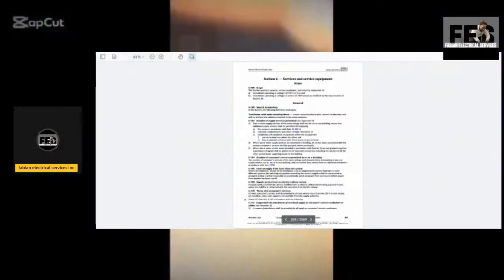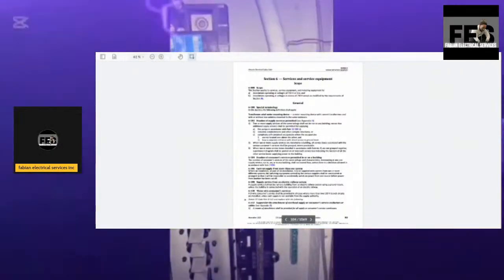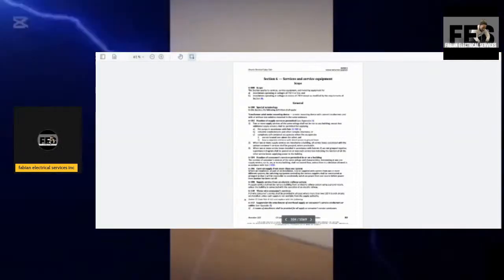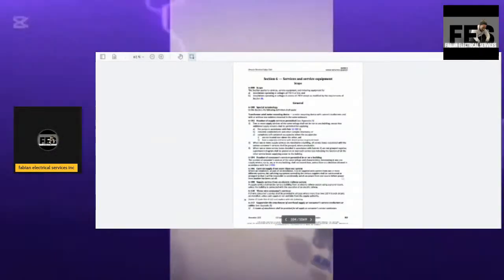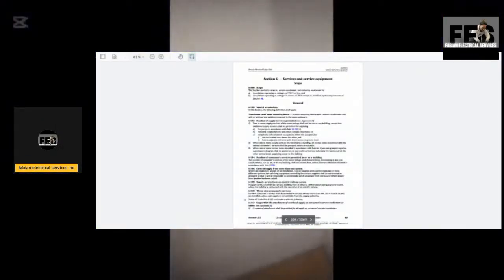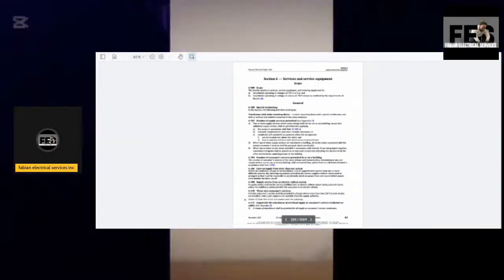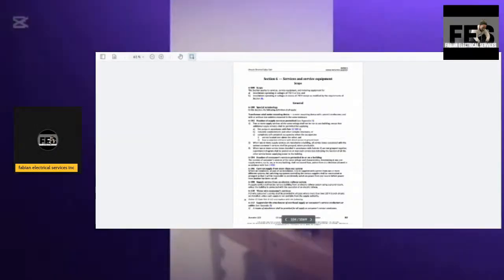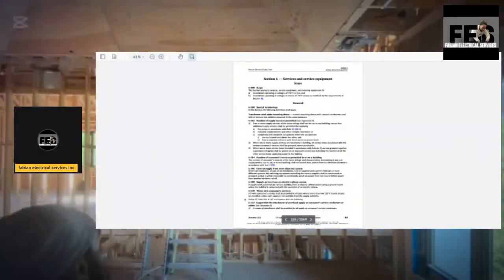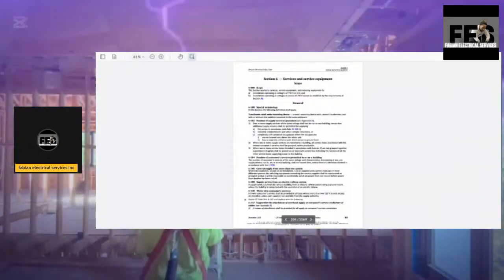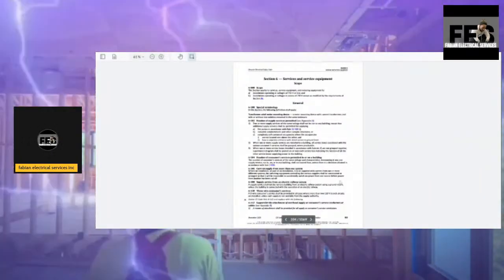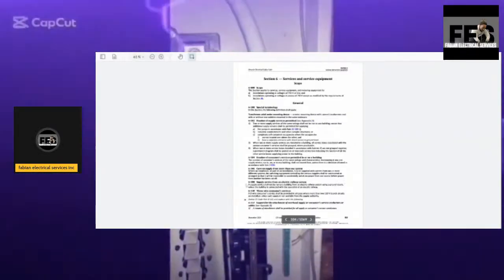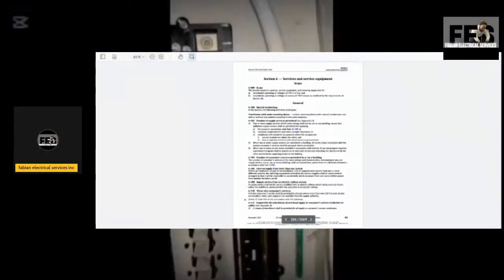Current supply from more than one system: when an installation or power of an installation is to be supplied with current from two or more different systems, the switches or equipment controlling the various supplies shall be constructed or arranged so that it will be impossible to accidentally switch on power from one source before power from another has been cut off.